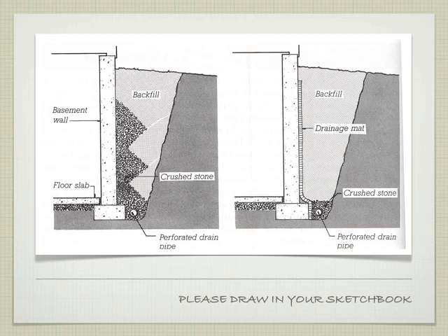So a lot of times, in order to prevent this from getting clogged, the fabric that's on here, the filter fabric, they'll go ahead and put this crushed stone in front of the drainage mat, to make sure that not all of the dirt is right up against this, clogging it up, not having it work. So it's very common to have the actual crushed stone as well. Depending on which drainage mat you pick, it might not be required.